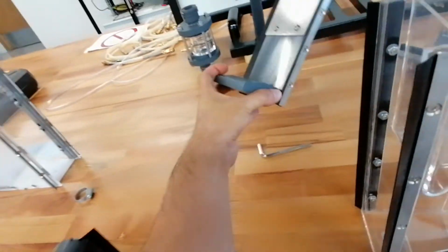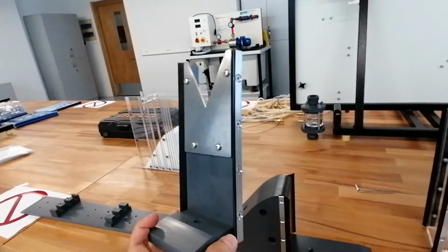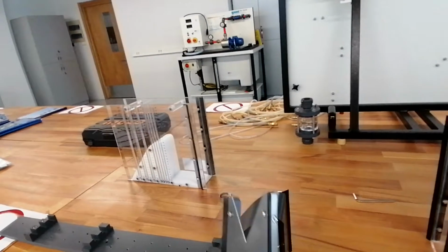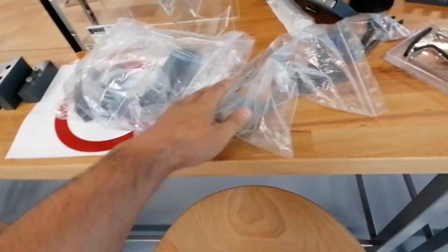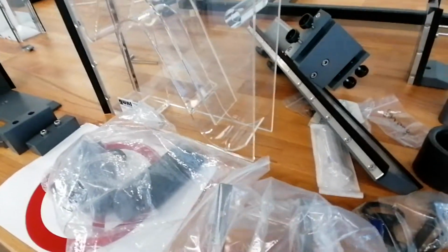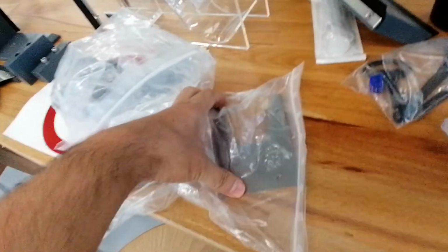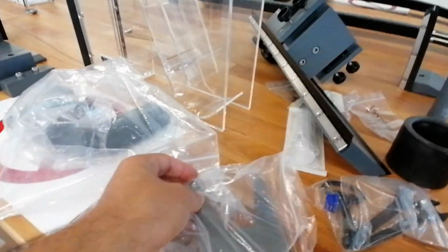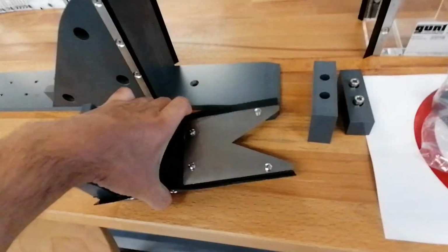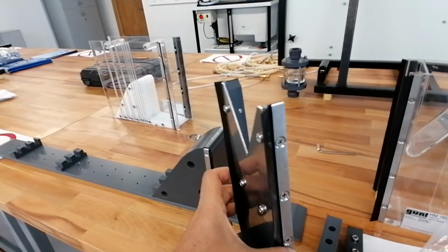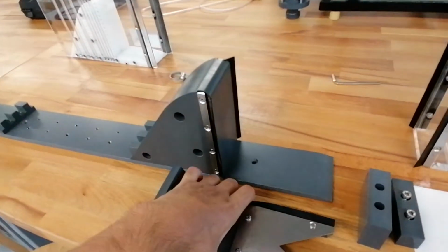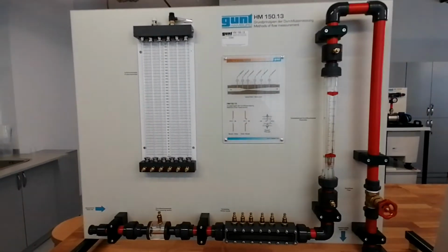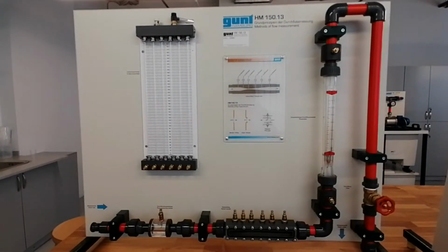So the other type of weir, you see a sharp crested weir, and this is a triangular shape, you see. And also we have other shapes for this. For example, this is rectangular, and this, as you see, is a trapezoidal shape. We can fix them to here to obtain different types of sharp crested weirs. Here there is another device. You see, we use this for flow measurement.